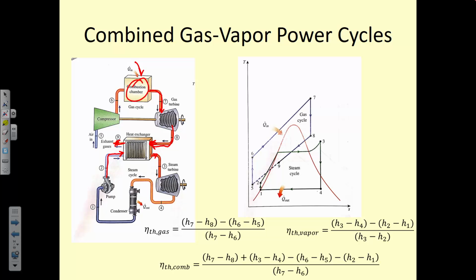And preferably it will be superheated at that point. So then we can exhaust these gases to the environment at a much lower temperature, which reduces environmental pollution as well as allows us to regain some of the losses from these exhaust gases by utilizing that heat that would otherwise be expelled. So then the steam runs through our steam turbine, similar cycle to what we've seen before. So this is a combination of a Brayton cycle and the Rankine cycle.